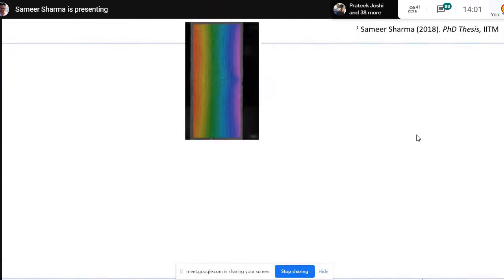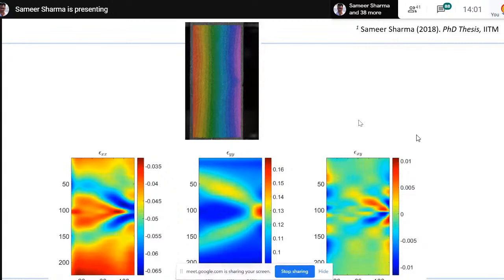Like I said, for example, look at this video. So to do material behavior, we do something called different tests. So this is something called a uniaxial tension test, where we just break it. You can see it, right? And then based on the deformation that you're seeing on the screen, we compute these stresses and strains. You can see that on the right middle, somewhere in the middle, there was a nucleus that started, there was a notch that gets started and propagated throughout the width.